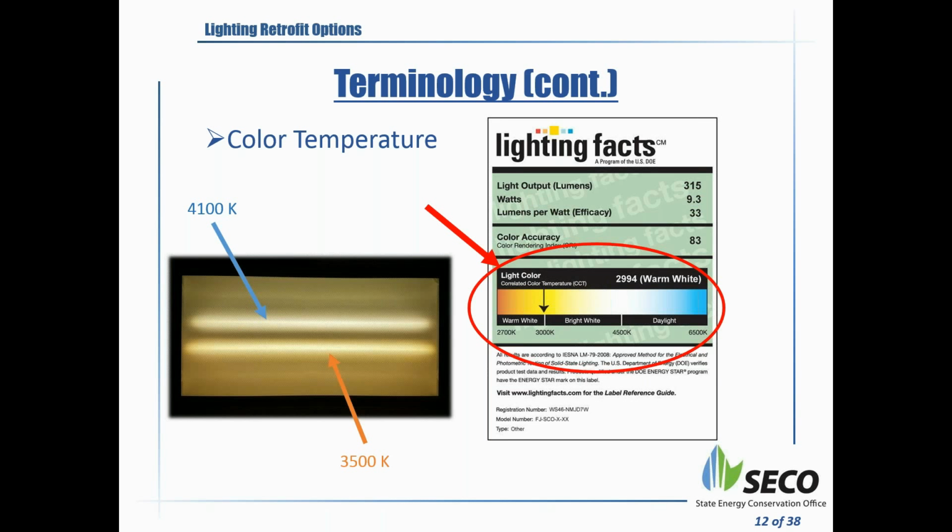The 41K is predominantly what I've seen, but a lot of times the purchasing department would order equipment because they're all T8s, and by mistake they may put 35K. So you get a mixture of 41K and 35K, which sometimes gives people the appearance that we have older fixtures or don't have a good quality light. This is something important to keep in mind.